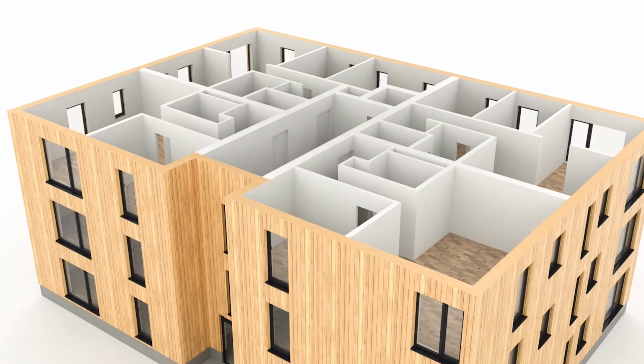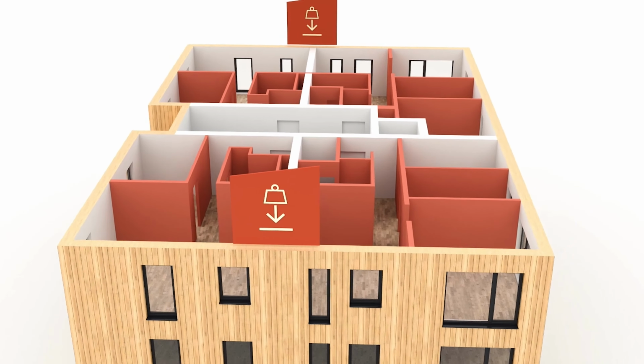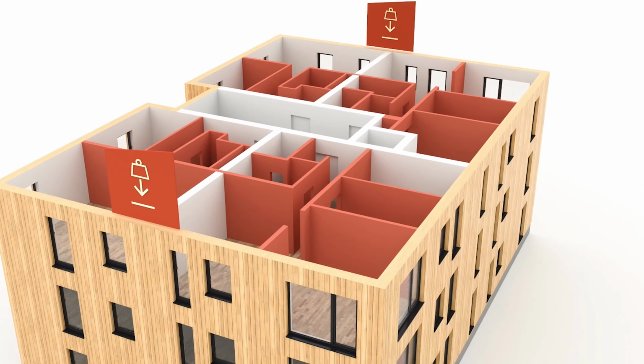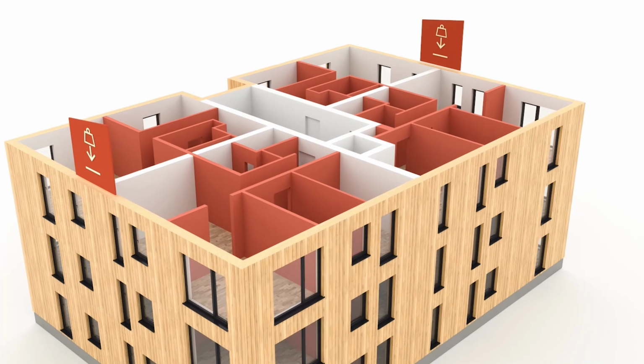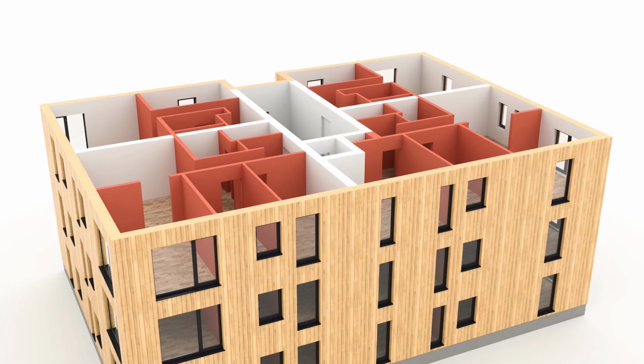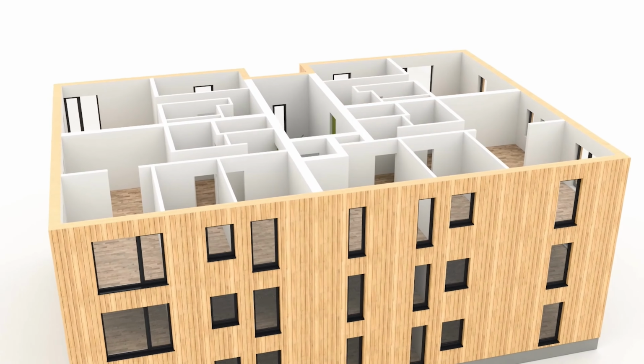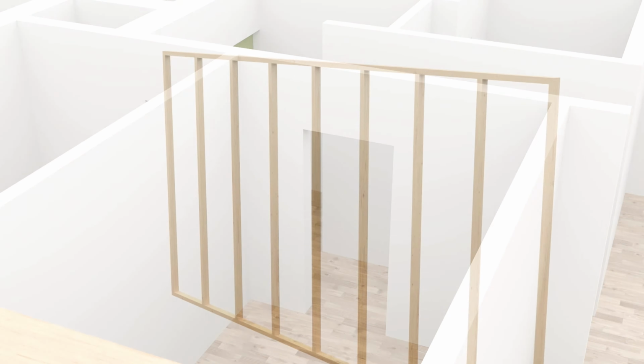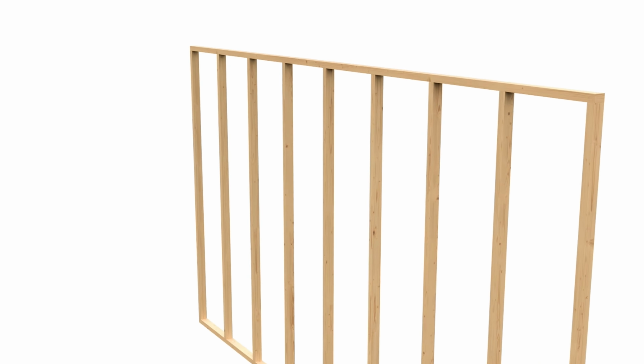Vertical load is a weight or pressure that is applied from top to bottom. For example, the weight of snow applied to the roof of a building, or the weight of the ceiling applied to the walls of the room, or the load caused by people on the floor, and so on. As a rule, the inner wall frame is slender, for example, mostly made from 45 to 70 millimeter or 45 to 95 millimeter wooden beams, between which there is mineral wool for sound insulation, and the frame is usually covered with plasterboards, but wood-based boards can also be used.